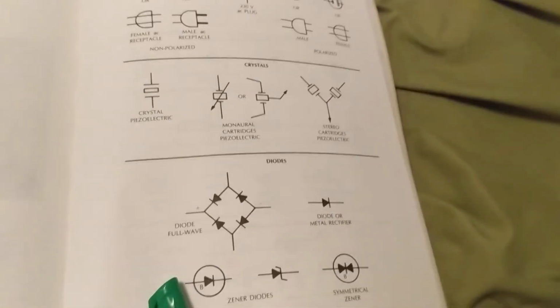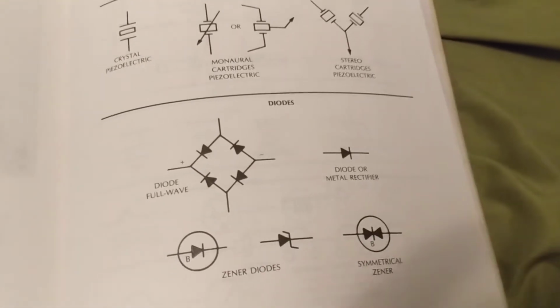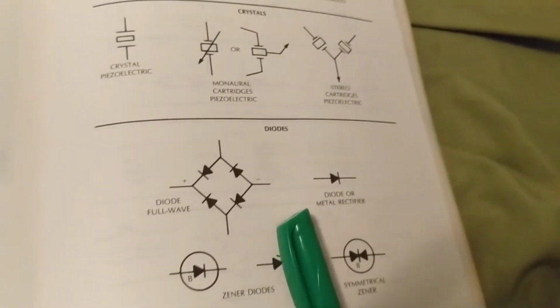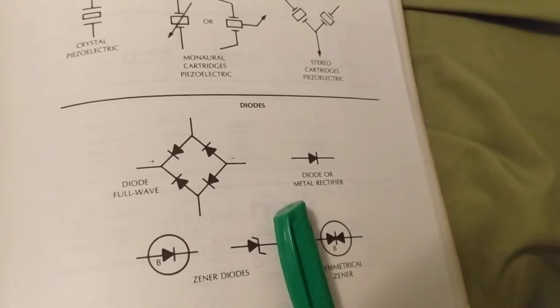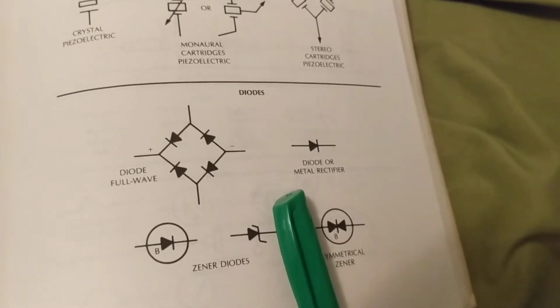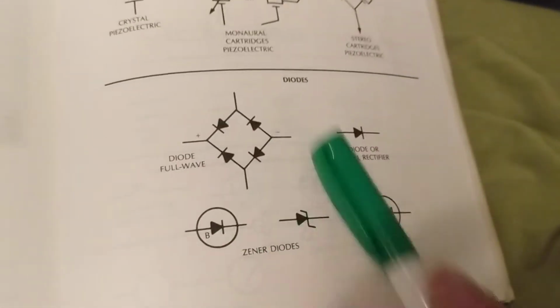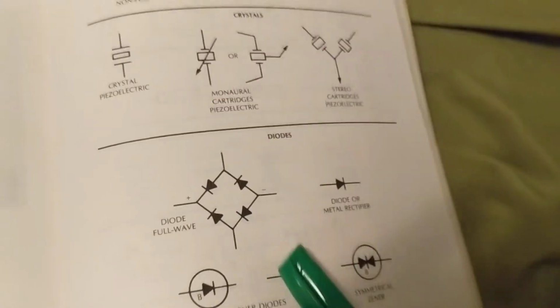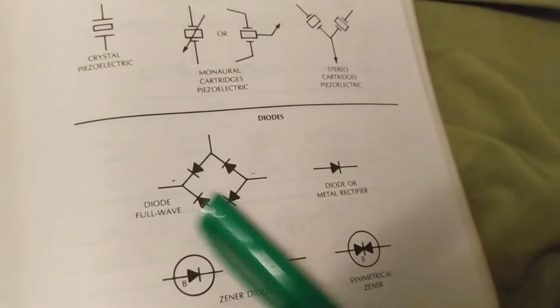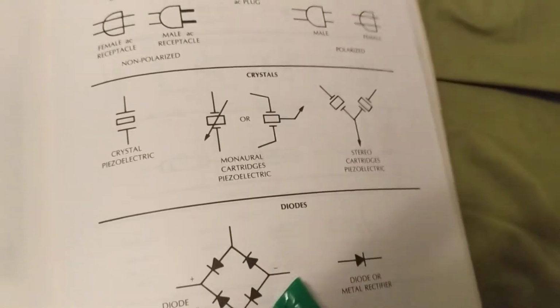Over here, as you can see, diodes, they are in the alternator. Alternator is an AC generator, but obviously we need something called DC to recharge the battery. That's where diodes come in, and diodes are in the alternator. They change the AC to DC. And many times you'll see something called a full wave or a bridge rectifier. But again, you don't have to worry about these things.